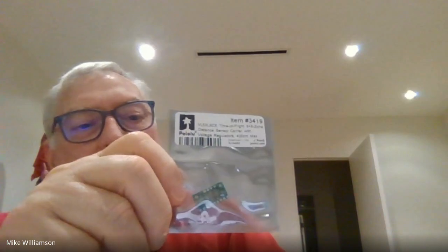But I would collaborate with Scott about these 8x8 time of flight sensors. I did have to do some kind of a trig function, a sine or cosine function, to straighten it out, because when I looked straight at a wall, it showed me a curve, and so I flattened it out by giving it a little scale factor using a sine function.